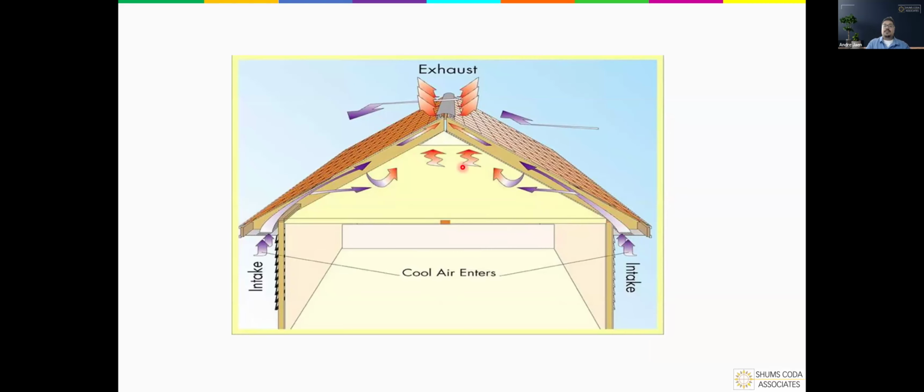In this case, when we have a vented attic space or we have enclosed rafters that are getting vented, then we are using this space effectively to be able to take air in from the bottom and exhaust it through the top, which is going to hopefully have a cooling effect overall on this roof, help normalize some of that temperature, but also it's going to pass that air through to make sure that we're not sealing that in, creating a dew point. It's going to help move some moisture out of the space as well when done appropriately.